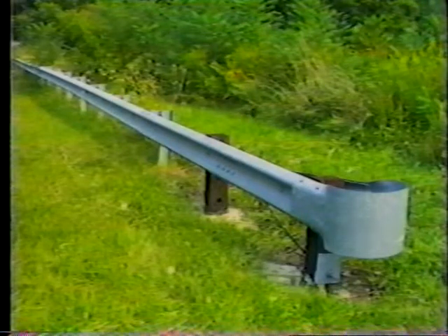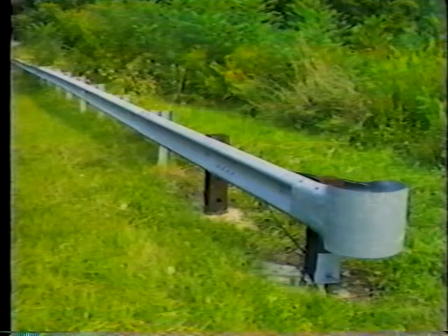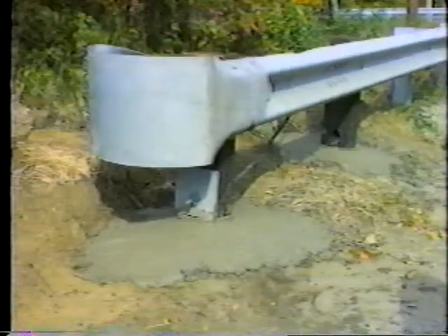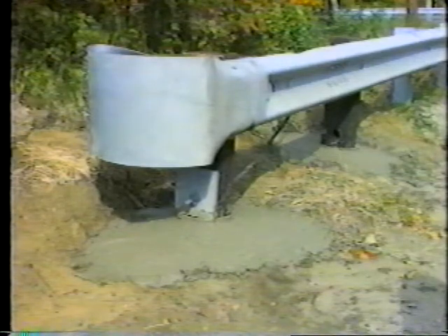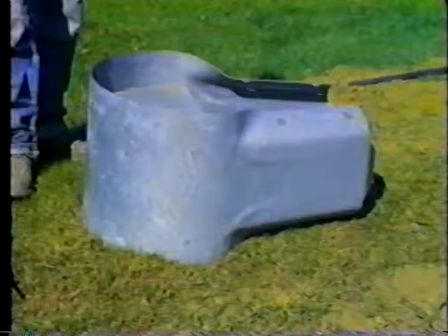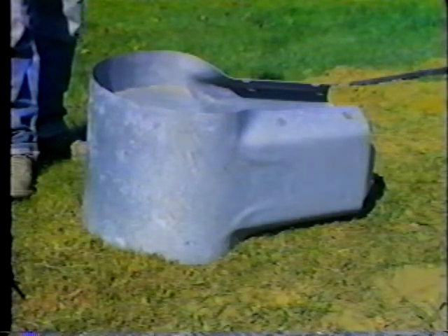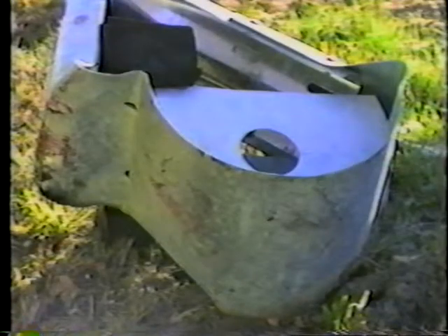Depending on the size, weight, and speed of the impacting car, beams in the end treatment continue to buckle until the vehicle is stopped. A bulb on the front of the system is intended to distribute a head-on collision's weight and force. It flattens out, preventing the W-beam rail from spearing the impacting vehicle. Here's a new bulb just prior to installation, and one that's been hit and done its job.